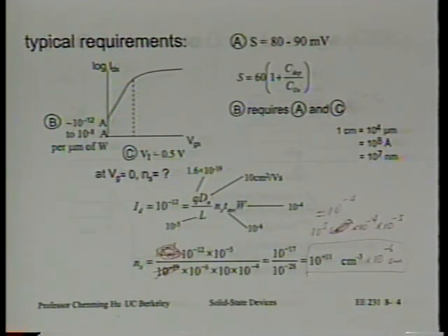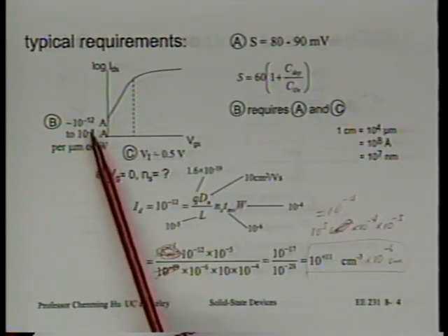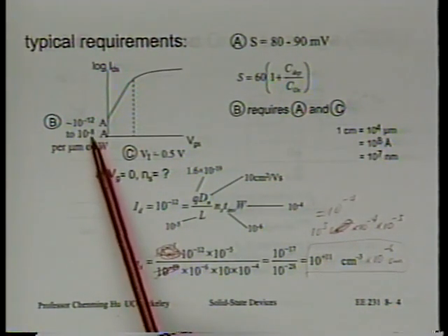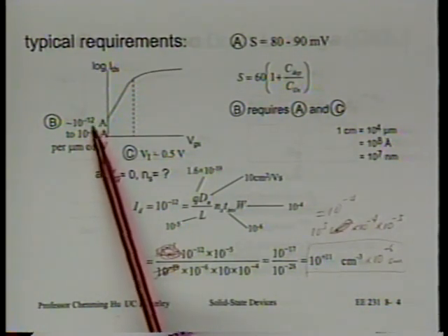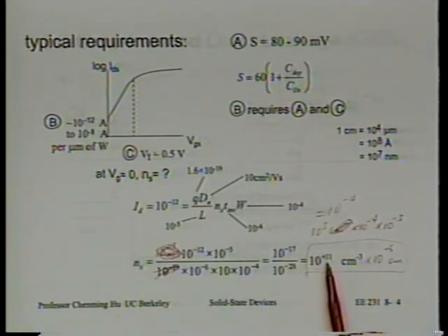All right? Now, if we're talking about the high-speed, low VT transistor with leakage current that's 4 orders of magnitude larger than the example we used, then we'll be talking about what? 10 to the 15th, right? That's also a good number to remember. So we're definitely not talking about no electrons at the surface, even though we're in the off state.